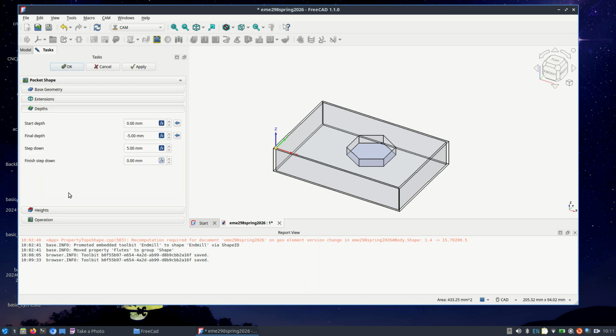No, depths. All right. So this is the start cut depth. Where are we going to start? At 0, because our origin is up here. Remember, I put the origin up there. So we're going to start at 0. And where are we going to finish? Final depth is actually -5, right? Because that's the depth of the...